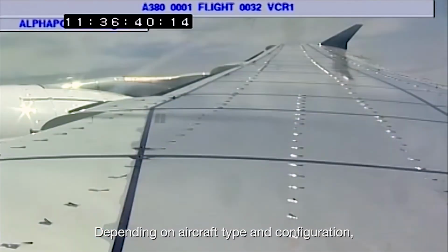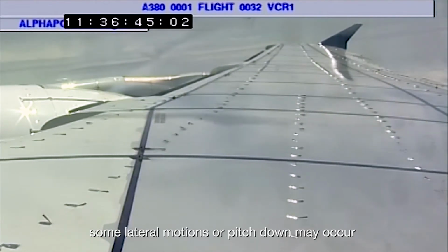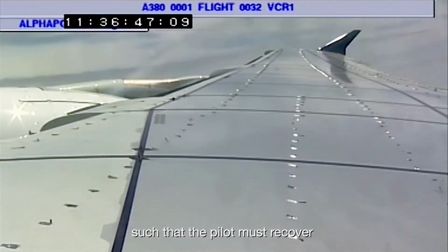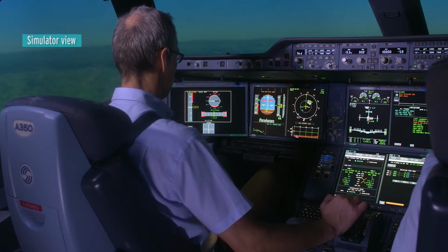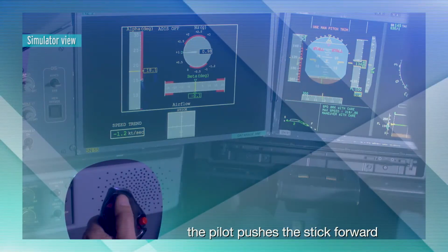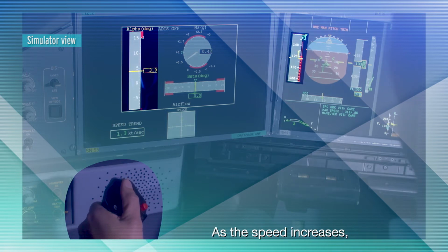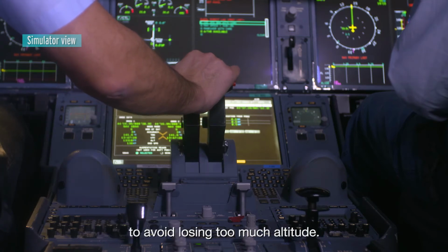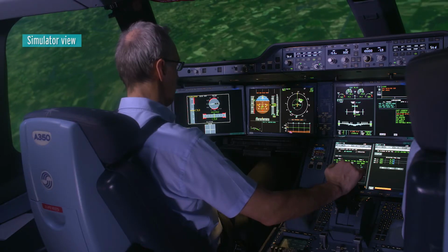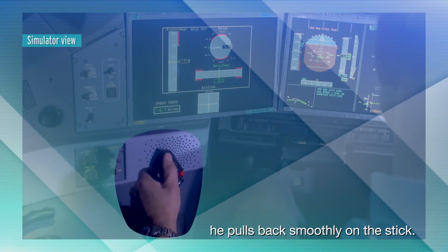Depending on aircraft type and configuration, some lateral motions or pitch down may occur, such that the pilot must recover before the announcement by the engineers. For recovery, the pilot pushes the stick forward to decrease the angle of attack immediately. As the speed increases, he gently adds some thrust to avoid losing too much altitude. When the speed is sufficient, he pulls back smoothly on the stick.